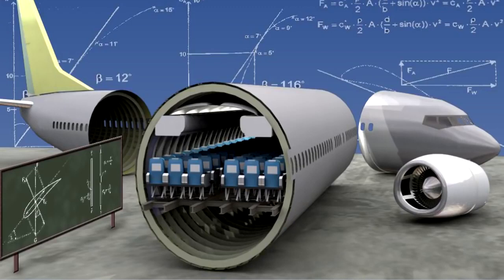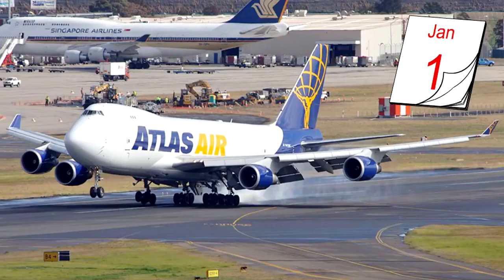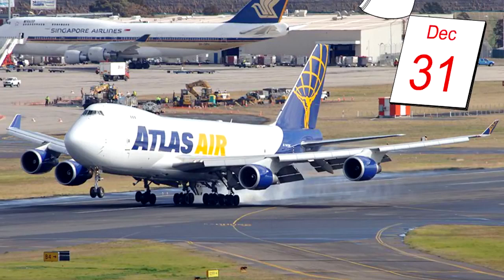So, for instance, aircraft designed for long-haul operations should not be used for short-haul, as the extra takeoffs and landings will not have been accounted for in the airframe's anticipated fatigue life calculations. The safe life of an aircraft structure is defined as the minimum life during which it is known that no catastrophic failure will occur.